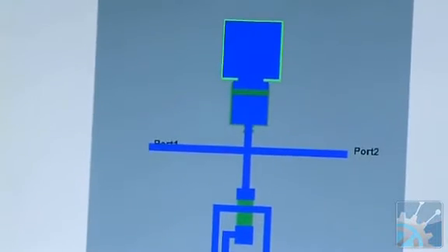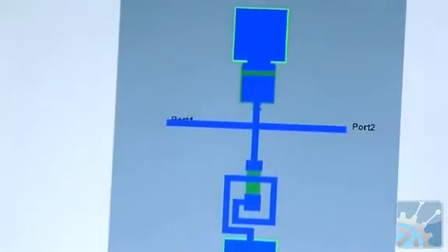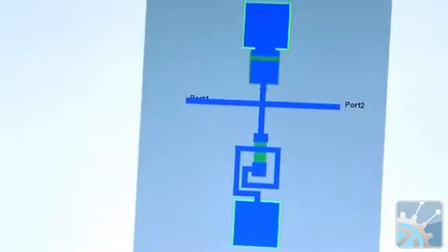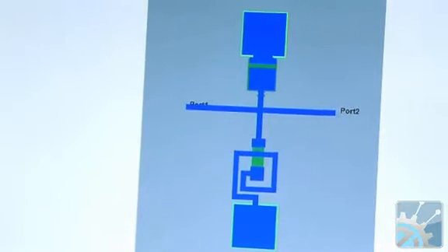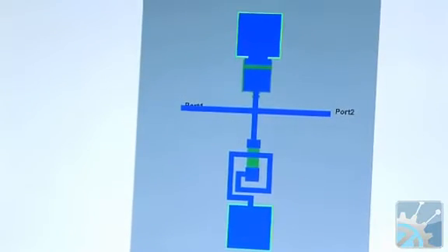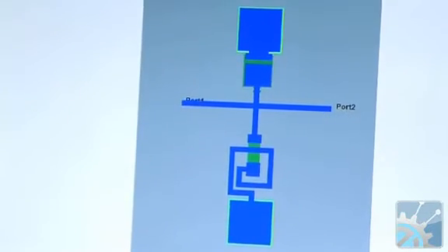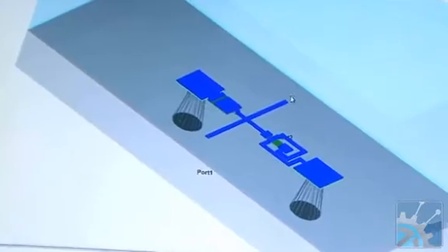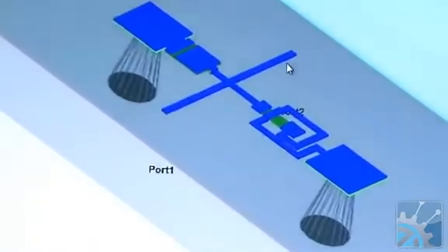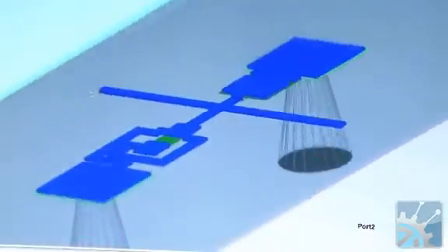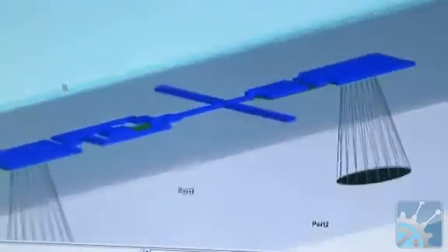But ultimately, especially in modern designs, these designs, which years ago might have been tackled by a 2.5D code, such as a method of moment space code, now need the rigor of a full 3D solver like you have with HFSS. So in such a design, we really do have 3D entities. We have thick conductors, we have test fixtures, etc. So we really need the rigor and accuracy of 3D.